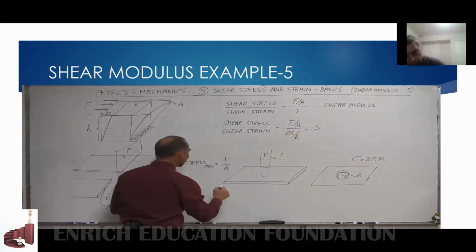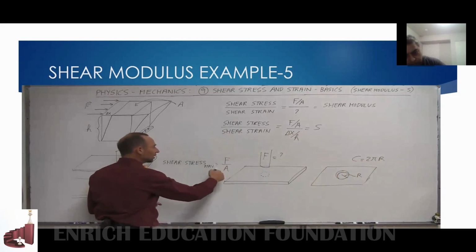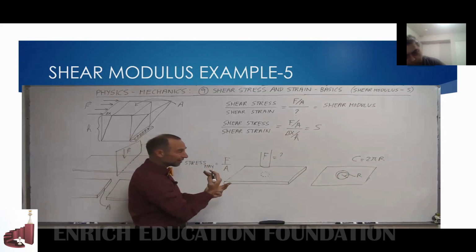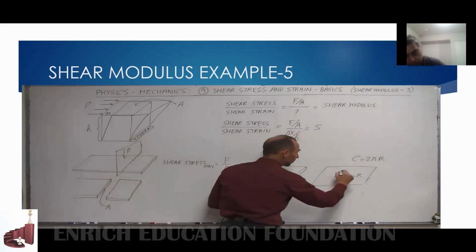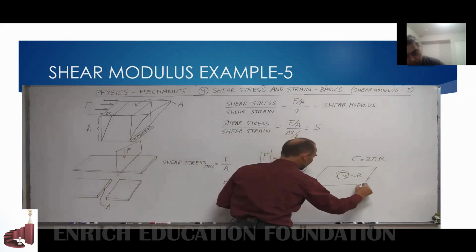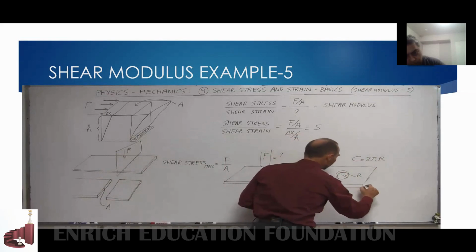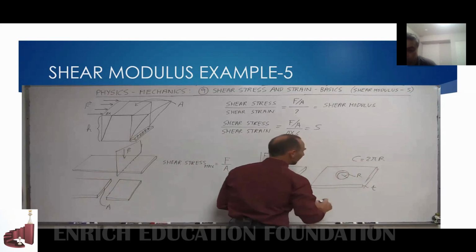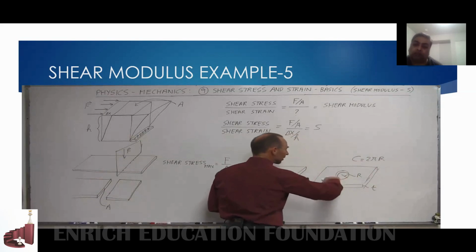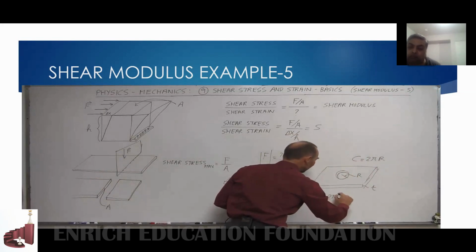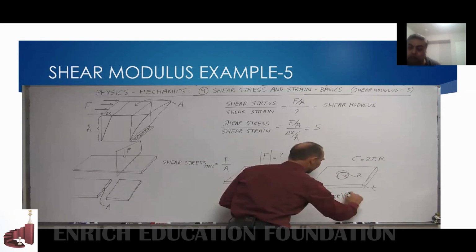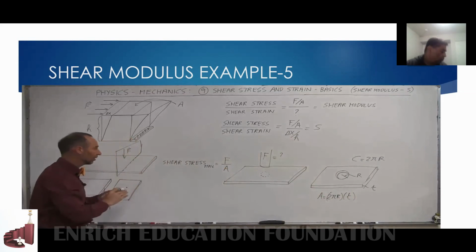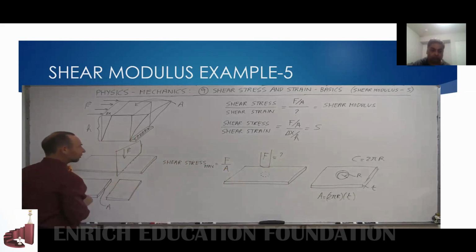So it turns out, again, the cross-sectional area that we're interested in is simply the area left by the side of the hole. So if you say this is the thickness of the material right here, let's call this T for thickness, then the area here would simply be the circumference of the hole, 2 pi r, multiplied times the thickness T, and that now gives you the cross-sectional area of the cut, which would be kind of the same as the cross-sectional area of the cut here.